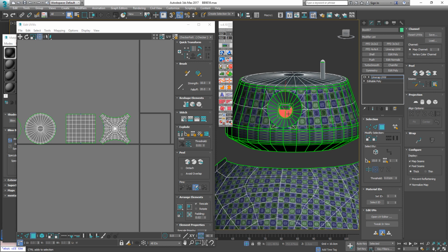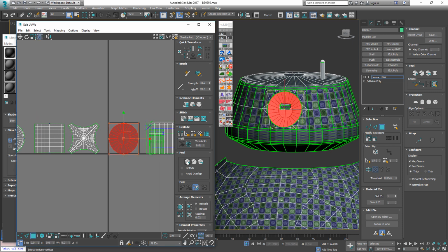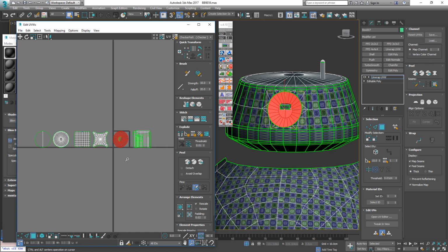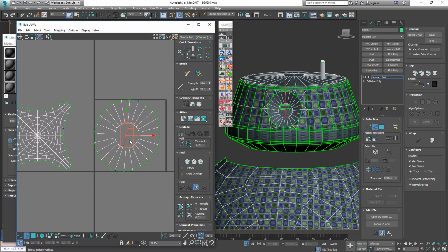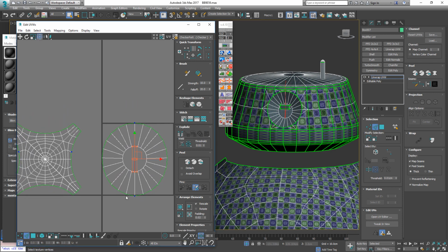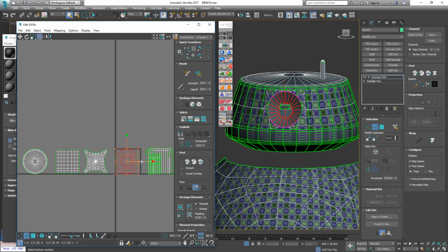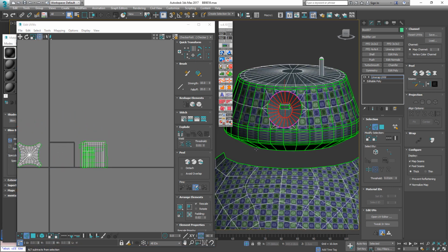And then let's carry on here in the center for the camera eye. Quick planar and a quick peel. And then let's switch over to edge mode here. Select the center edge and in the text tools, click on align. That way we have it perfectly horizontally aligned here as we see it there in the 3D viewport.